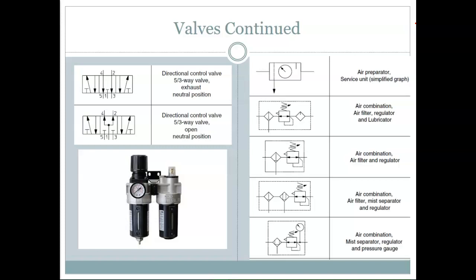So what you have is air being dried out through compression and filtration. And that's good because we do not want water in our system ever. It wreaks havoc like crazy. So what do we do? We filter it 7 ways to Sunday. However, dry air is not great for components because it takes all the moisture away from those components.